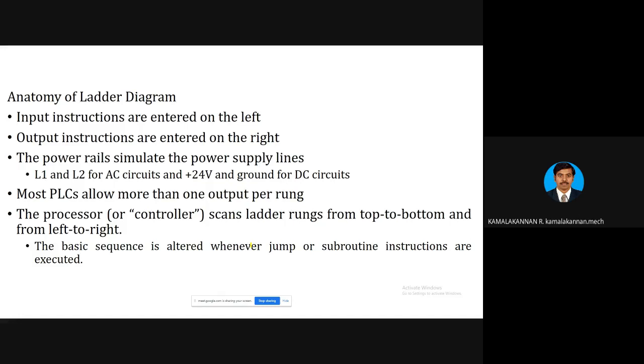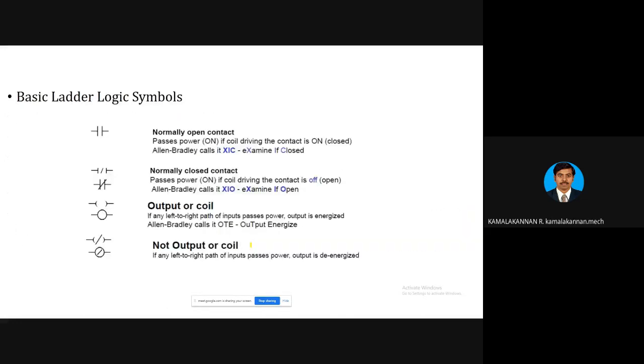In an exam you can draw the ladder logic drawing, but for writing a program for a PLC there are many software packages. In that you have to prepare the ladder logic drawing, and you have to send that ladder logic to the PLC. As I told you, you have some external device through which you can connect and send the program.